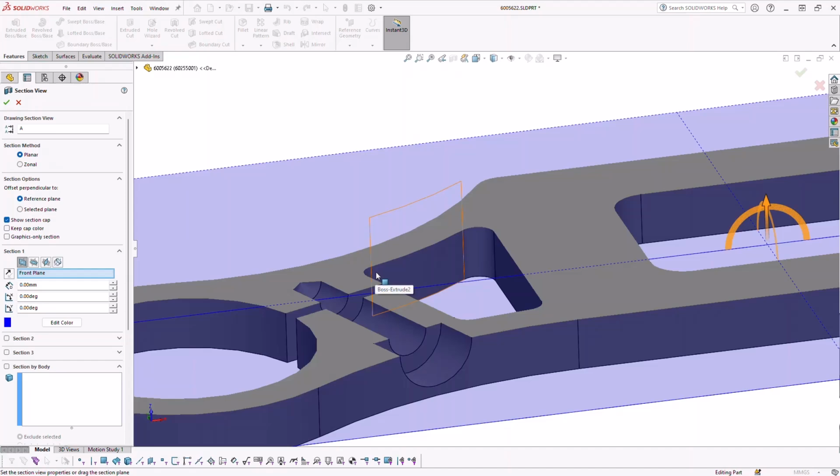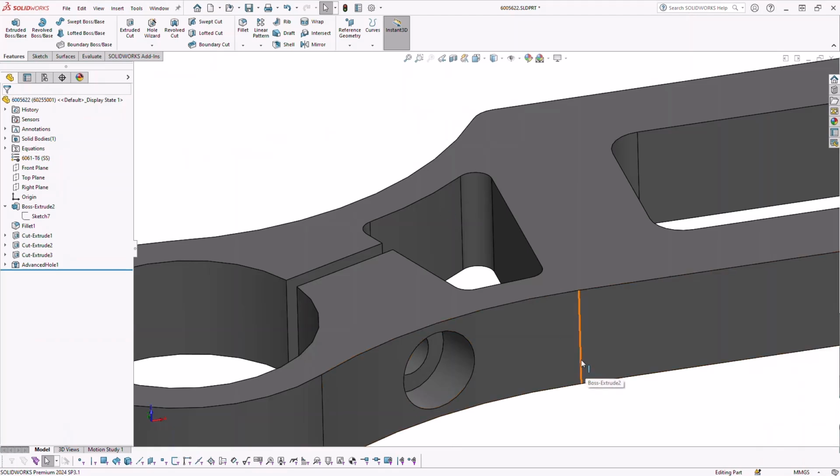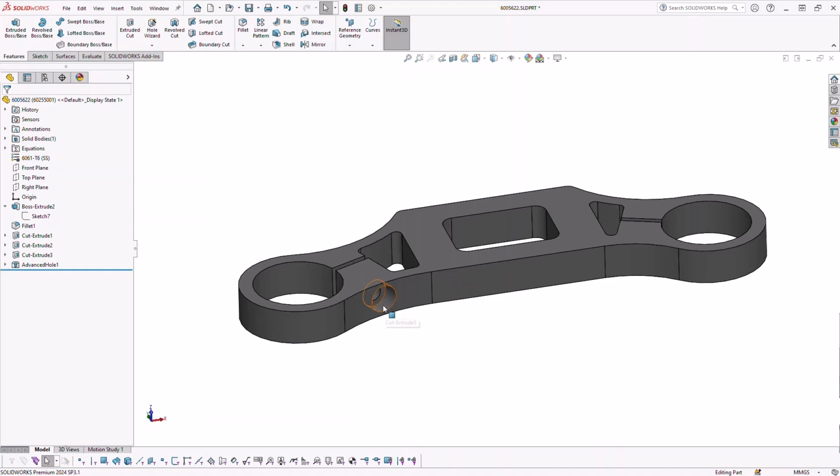Looking at the modelling section, you can see both the elements of the advanced hole and the original cut feature that created the clearance for our bolt head. I'd like to reuse this set of features on the other side of the model so that they will both update if I change them, so it makes sense to use a mirror feature.